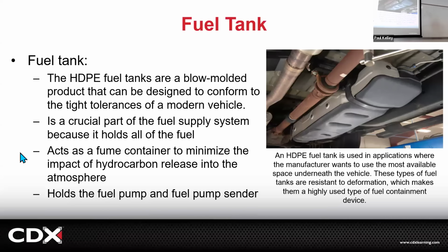Makes sense? Did you know if you had a hole in that fuel tank, you'd get the same check engine light? If it's all the way at the top of the tank, you might not see any fuel leaks, but that system will sense that that tank is not holding pressure and containing hydrocarbons. Check engine light's on. If it's a small one, it may be a very small evaporative emissions leak. If it's a big one, it may be a gross evaporative emissions leak, which isn't because it's nasty. It means it's totally not holding. It's grossly failed. It's complete.